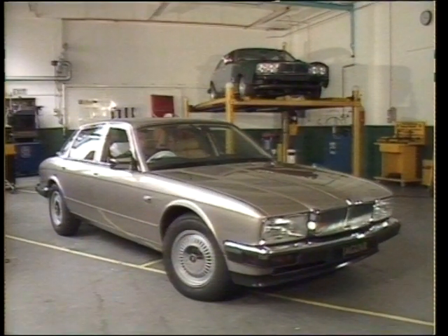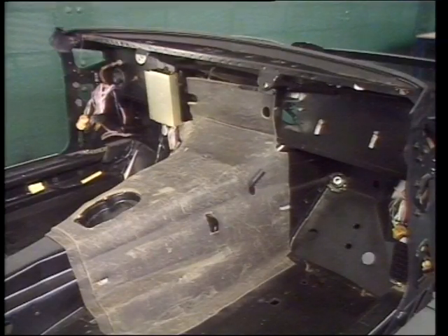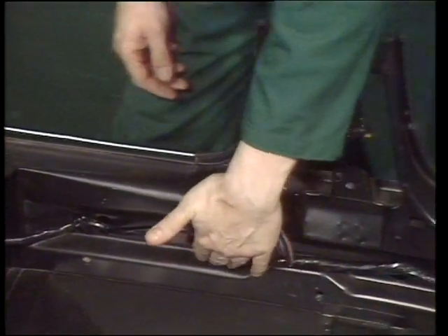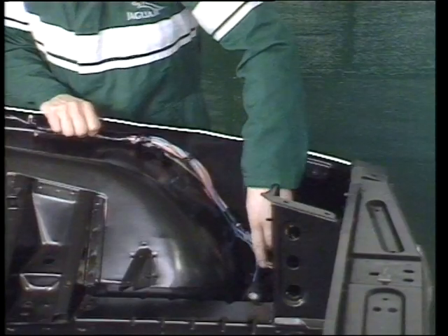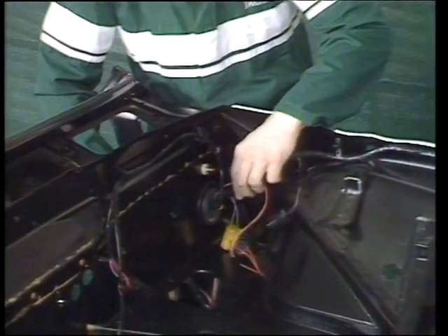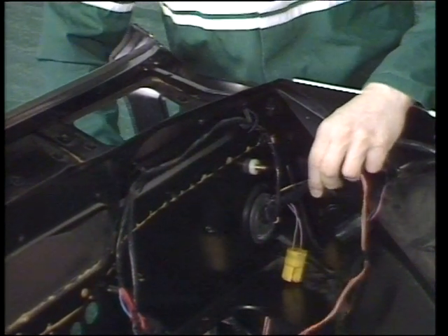The XJ-6 electrical systems harness consists of 2 side harnesses running the length of the car, joined together by the bulkhead harness which runs behind the dashboard. On this cutaway car, we'll be following the left-hand side harness and the bulkhead harness, showing the points where they're joined and the run of the harness through the body shell. Starting at the front left-hand lamp relay module, the left-hand side harness runs through the engine bay and onto the left-hand side bulkhead grommet, located in the A-post.